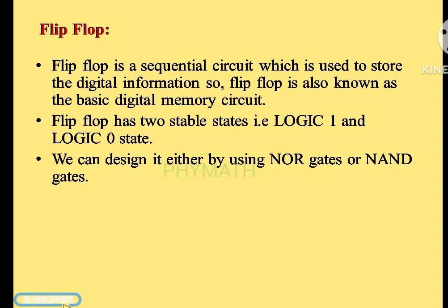As we know the basic difference between the combinational circuit and sequential circuit, the output of combinational circuit depends only on the present input and it doesn't depend on the past status of the input, so it has no memory. But the output of sequential circuit depends on present as well as past output. So to provide the past input or output, a memory element is required. So for sequential circuit, flip-flops are used as a storing element.